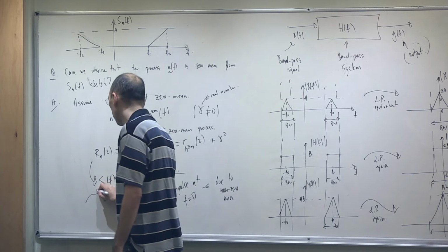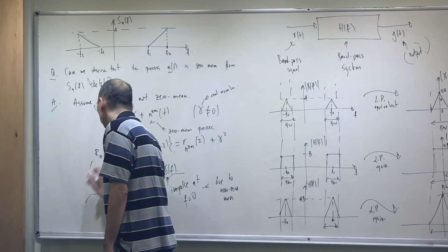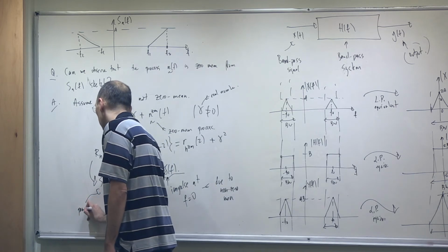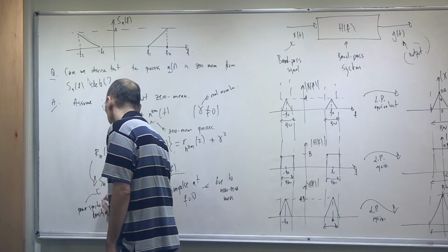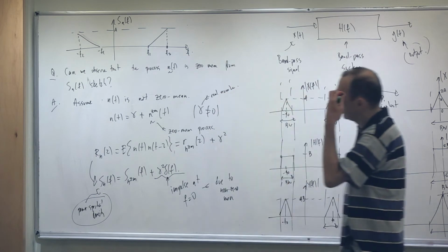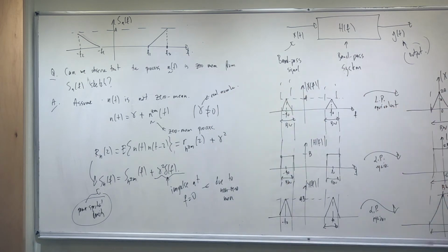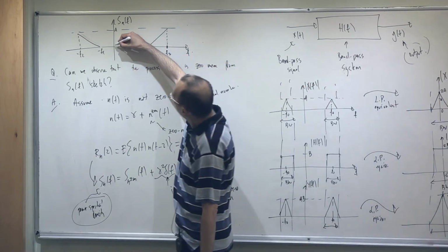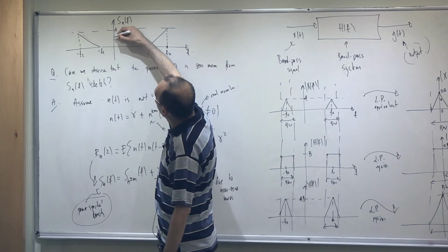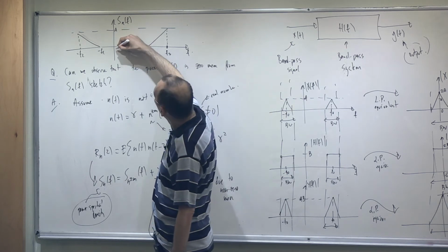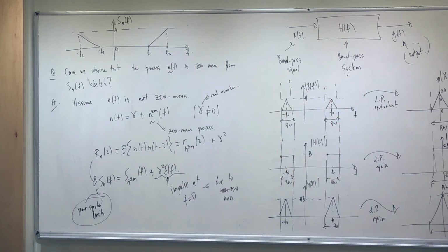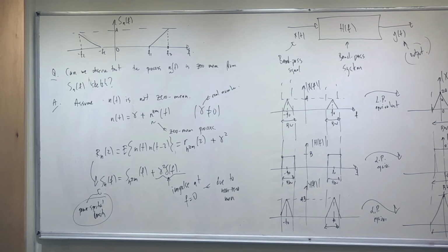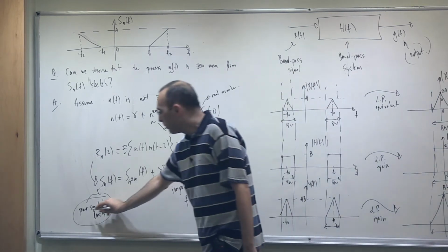But let's pay attention to this power spectral density. I mean, this is what we do all the time. If this is non-zero mean, there will be an impulse over here. Okay? Clearly, at the origin, there should be an impulse. If you don't see an impulse, well, I don't need this information, perhaps, if I sketch that at the very beginning. Okay? Very good. So why am I writing here power spectral density?